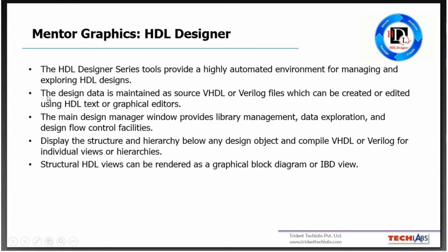And what are the other advantages? The design data is maintained as source VHDL or Verilog files, which can be created or edited using HDL text or graphical editors. That is nothing but HDL Designer has graphical editors where you can edit your HDL code and organize and compile in the same environment. The main design manager window provides library management, data exploration, and design flow control facilities. So all those things are present in HDL Designer.